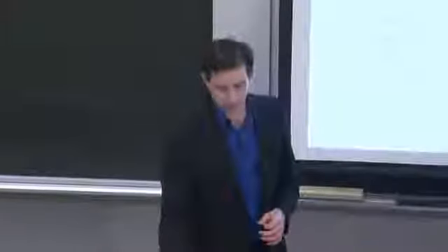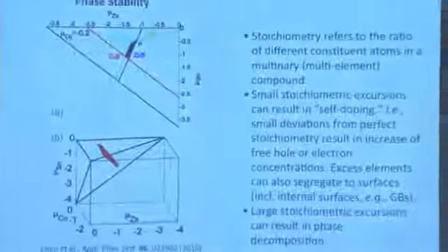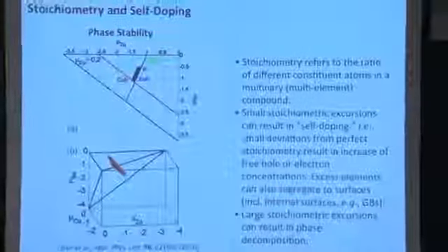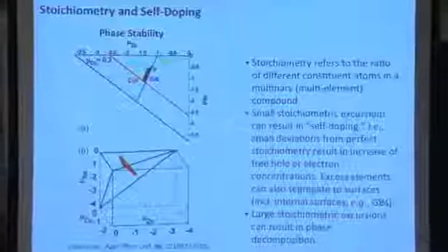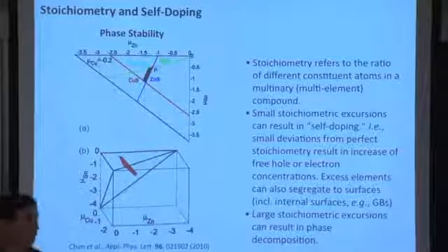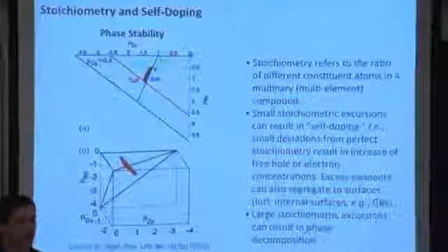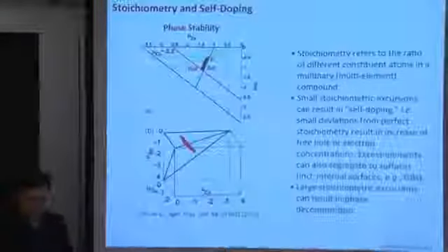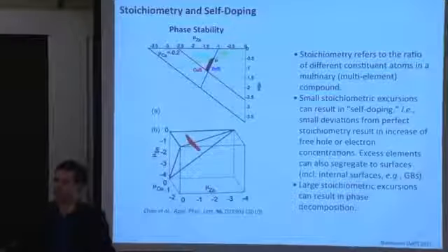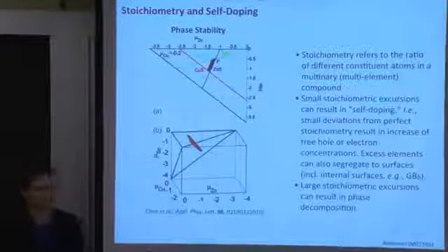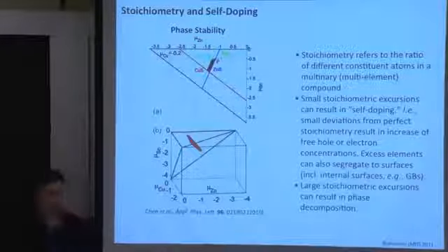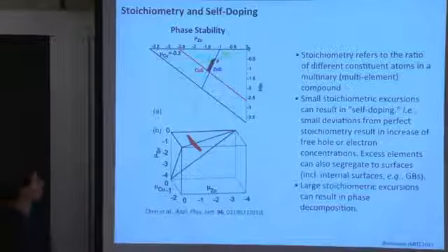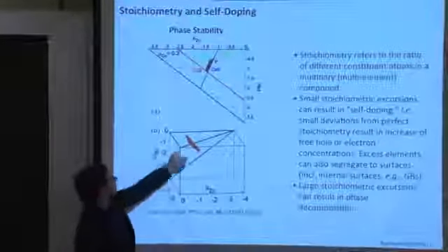OK, so general issues in thin films. Thin film compounds are typically, not always, but typically binary, ternary, quaternary, or multinary semiconductors, meaning you don't have just one element comprising the semiconductor species. You might have several. And they form a crystal structure with repeating structure, but alternating atoms typically. And so if you have multiple atoms in one compound, a couple of issues could arise that need to be controlled to grow good films. The first involves phase stability.